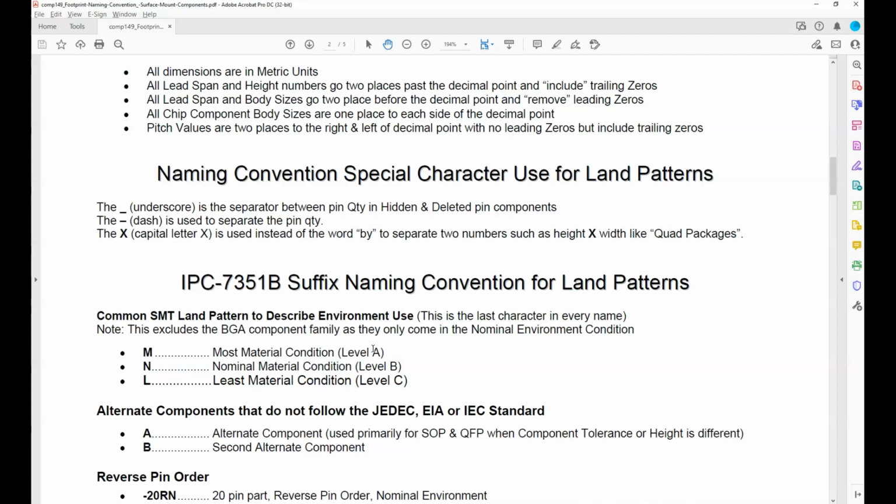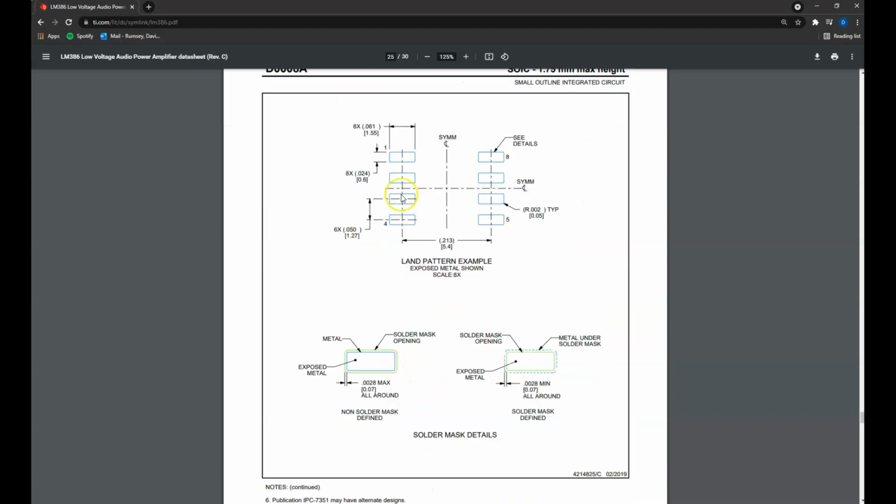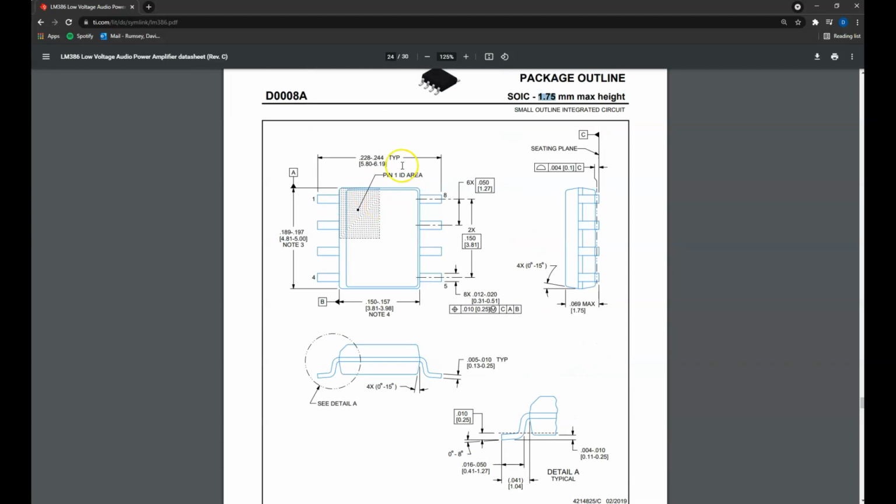I mean, we can, but in this case, we wouldn't be able to make the pad stacks any smaller because we used what the data sheet told me to do. I can't make those any smaller. And if I make the chip smaller, then that's a different package. So this footprint is basically going to just be for the other one.